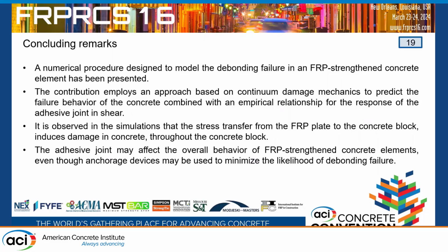So, some concluding remarks. A numerical procedure designed to model the debonding failure in an FRP strengthened concrete element has been presented. We have employed an approach based on damage mechanics, or a smeared crack model, to model the degradation of concrete. It was combined with an empirically identified constitutive relationship for shear for the adhesive.